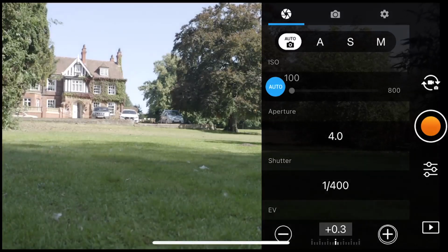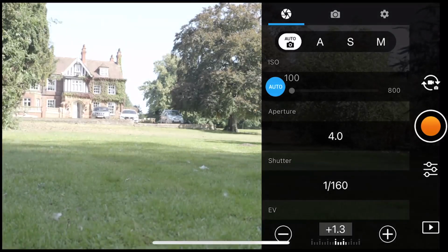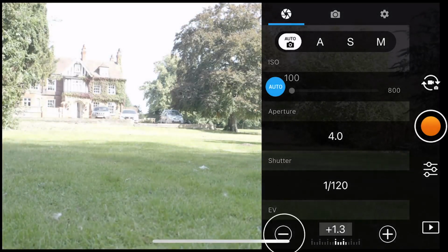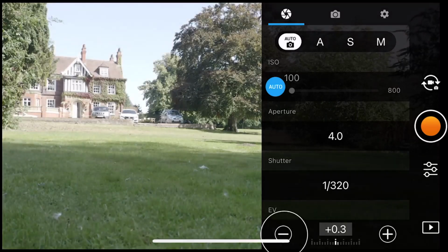If you don't feel confident to manually control the exposure of the image at this stage, the auto settings do a great job. Many pilots will set the drone to automatically analyse the light available and adjust the settings accordingly. We can fine-tune this by using the exposure compensation setting, which will increase or decrease how light our image is. Although manual settings are encouraged to have total control over the image and final output, auto settings can be useful in changing weather conditions and brightnesses to ensure you capture a usable shot every time.